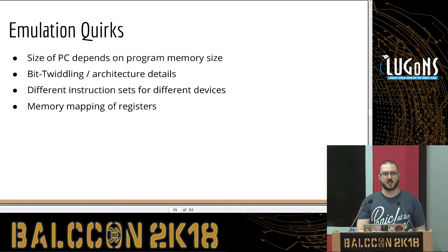So if it's enough, you can use 2 bytes for the program counter, but if you have a lot of program memory, you'll have to use 3 bytes. And you have to think of that when you use a call or a return instruction.